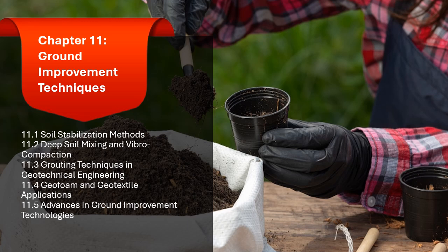Example: geotextiles are used in road construction to separate the subgrade soil from the base material, preventing mixing and ensuring better load distribution.